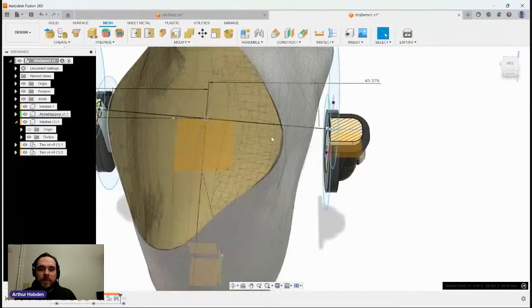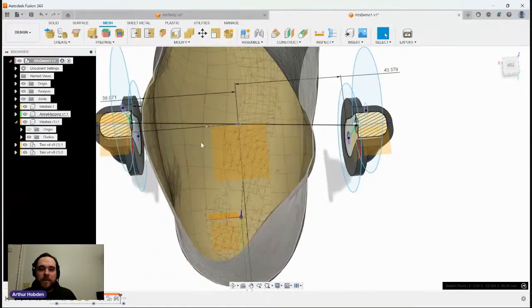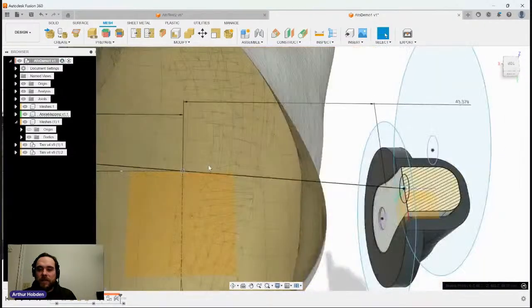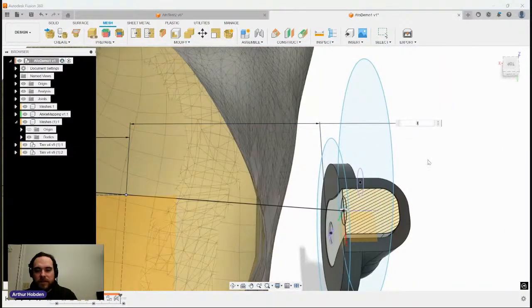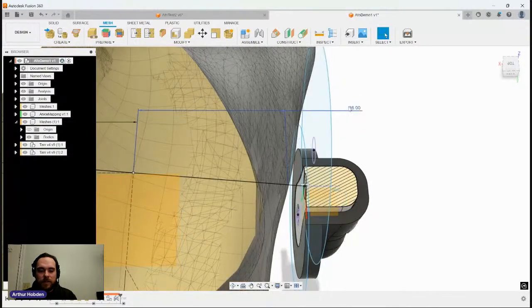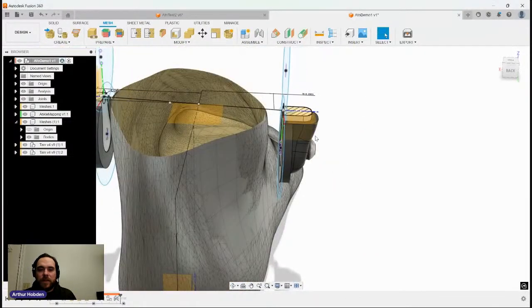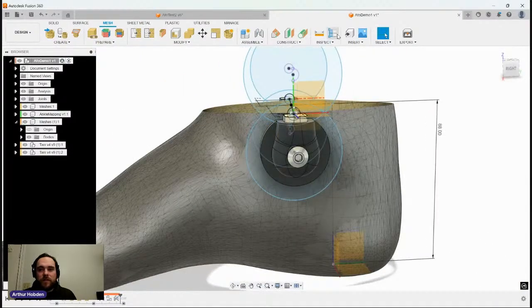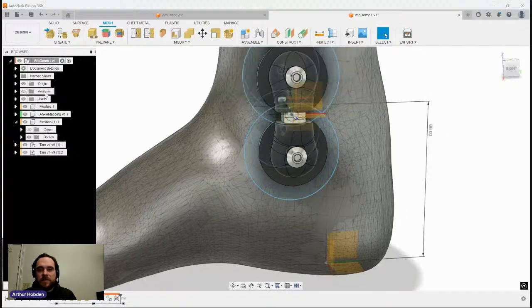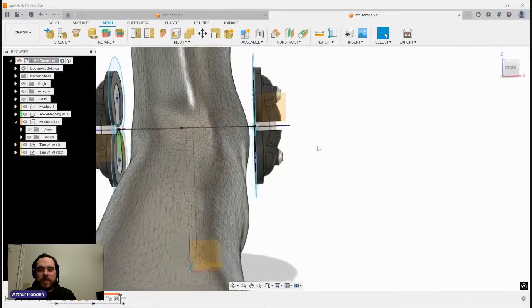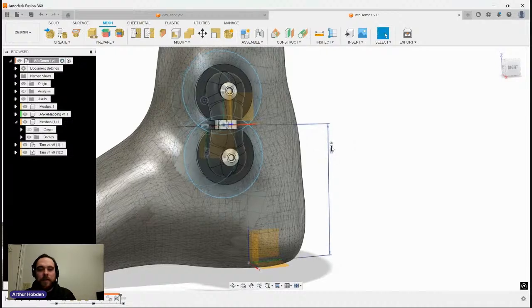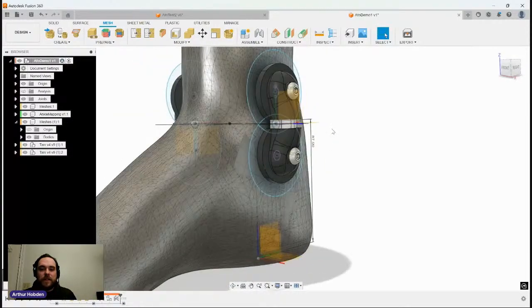So what I'm doing here is sort of a 5-degree tilt off of the medial heel bone at this highest point, and then I'm giving a 4mm offset from that. So this one's a little high. Let's change this down to 36, maybe 33. Let's try 33. Not close enough. Again, we can move this around a lot. And if I turn off my section analysis, we can see it's about the right height, maybe a little less. So maybe let's bring that down to 87. So we'll call that good for now.